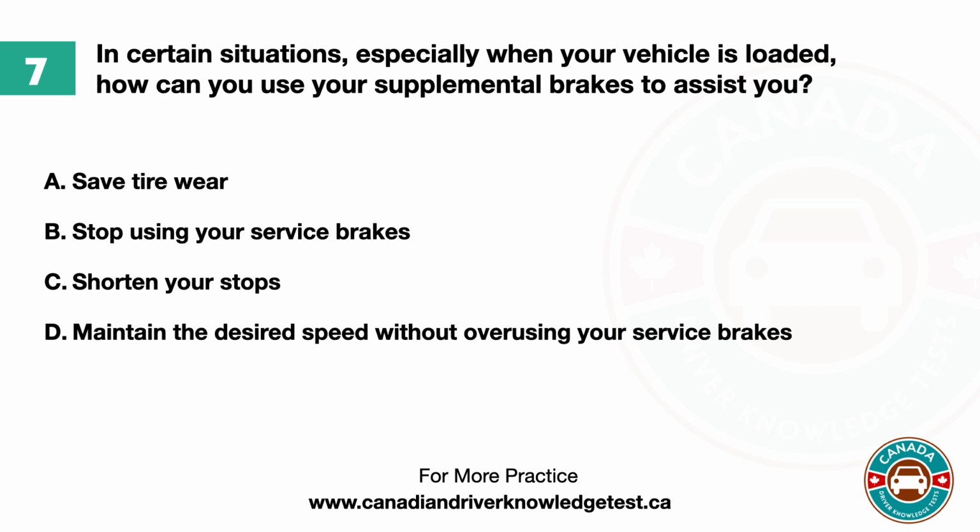Question 7. In certain situations, especially when your vehicle is loaded, how can you use your supplemental brakes to assist you? A. Save tire wear. B. Stop using your service brakes. C. Shorten your stops. D. Maintain the desired speed without overusing your service brakes. The answer is D. Maintain the desired speed without overusing your service brakes.